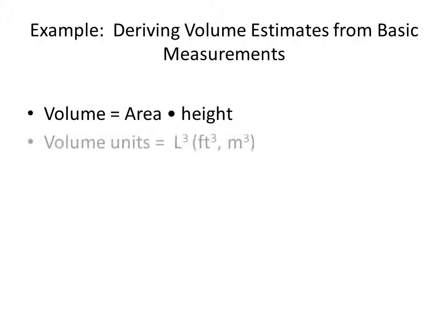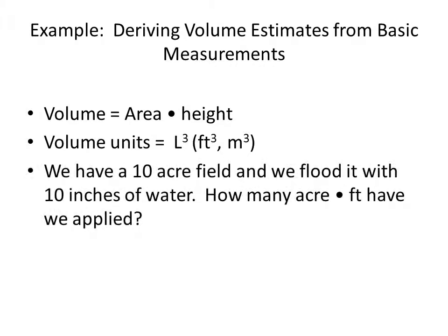An acre is a unit of area. Feet is the depth to which water is applied on that area. So if we take acre, which is our unit of area, and we multiply it times feet, one of the things we see is that we have then automatically come to this unit of volume, or this set of volume units, which is acre feet. In this case, though, we're given information about the area, acres, and we're multiplying that times the depth, which is given to us in inches.